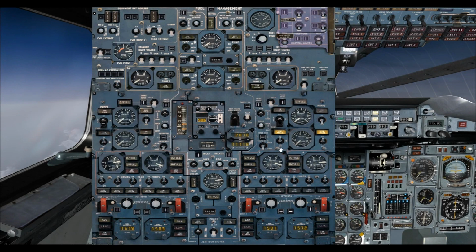All right, so we're reaching the end of the fuel in tank 8. I'm just going to turn off the 2 pumps in tank 8. We have a few hundred kilos of fuel left in tank number 6, and when that gets to 0, I'll be turning off the pumps for tank 6.